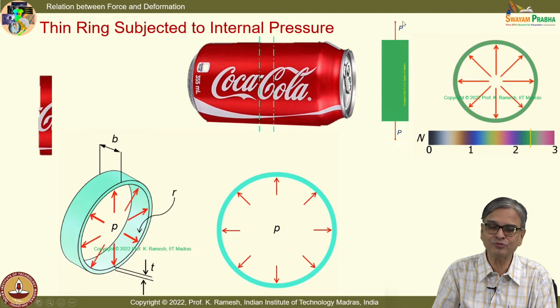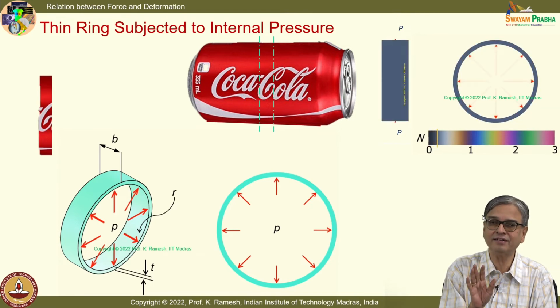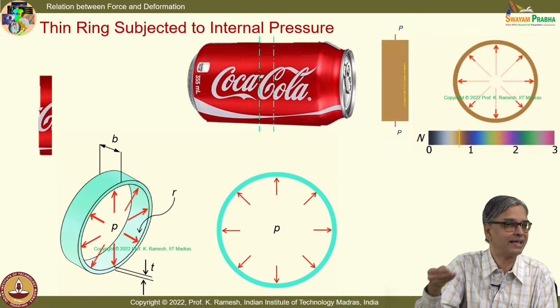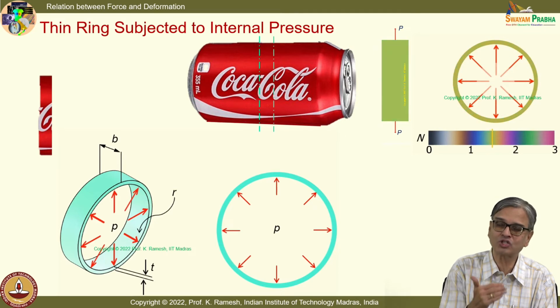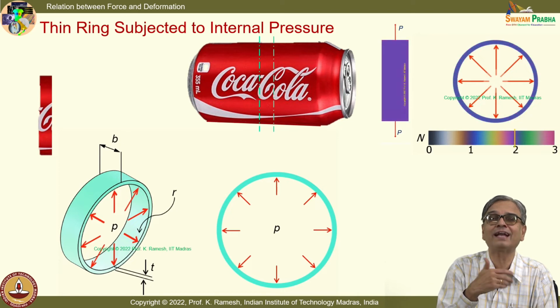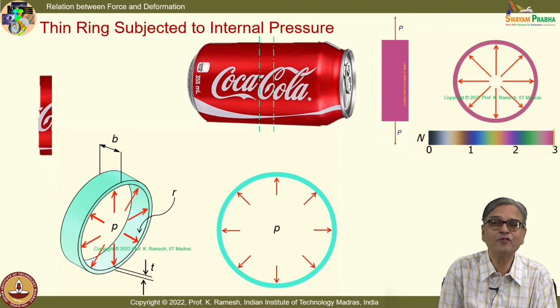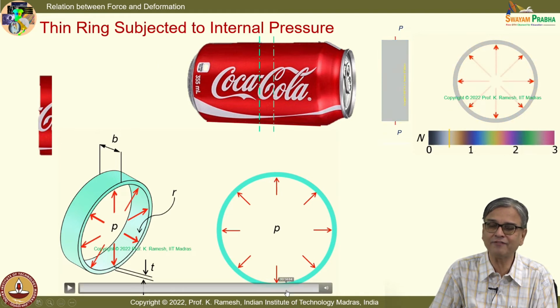And I have already given you a clue. I have shown what the fringes are in the thick cylinder and the thin cylinder. I have shown it as slightly thick for you to see. I can't have a simple line and then ask you to see the color. Only if I show some width will you be able to see it. Even before we solve the problem, you have a clue. Can anybody say what stresses are developed, in what way you anticipate the stresses developed in the cylinder? Is it uniform? Because if I have uniform color in tension, I see uniform color from photoelastic fringes.